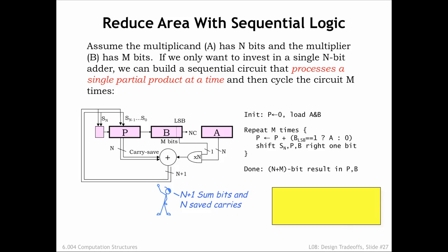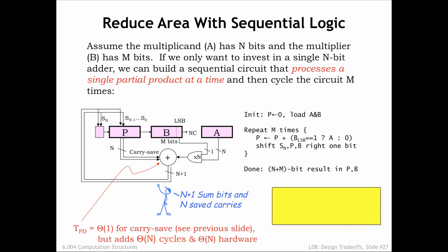The clock period needed for the sequential logic is quite small, and more importantly, is independent of n. Since there's no carry propagation, the latency of the carry-save adder is very small. In other words, only enough time for the operation of a single full adder module.